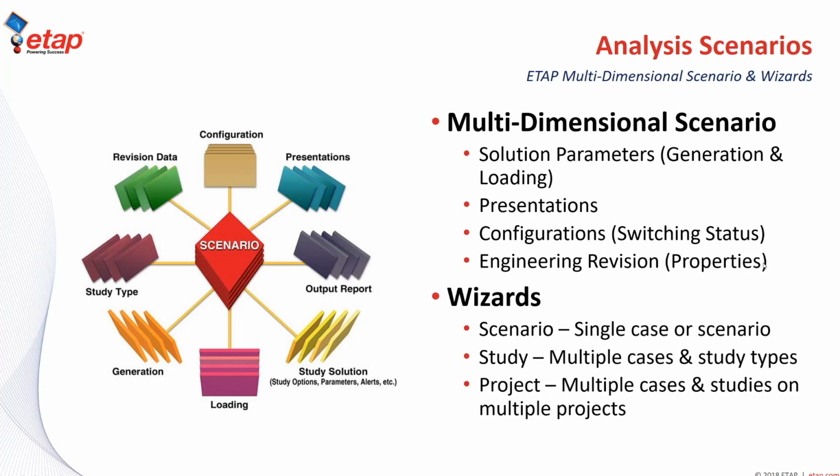Once these multi-dimensional scenarios have been defined and created in ETAP, they can be executed singly or in a batch using various study wizards. The very first study wizard in ETAP is called a scenario wizard. It allows the user to run a single case or scenario. A study wizard allows you to run multiple cases or multiple scenarios, which could be just for a single study like load flow, or it could be for various study types. That is, running multiple load flows and running multiple short circuits at the same time.